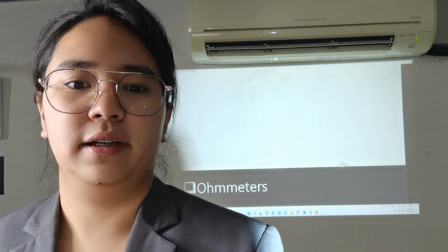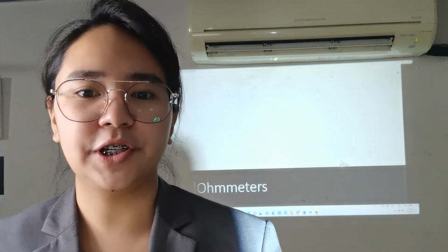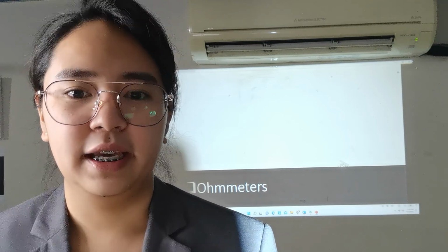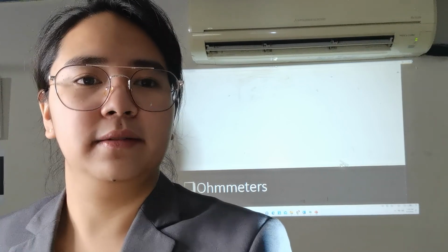And then the next is ohm meters. The ohm meter consists of an internal battery in series with the meter movement and a current limiting resistance. You can see.